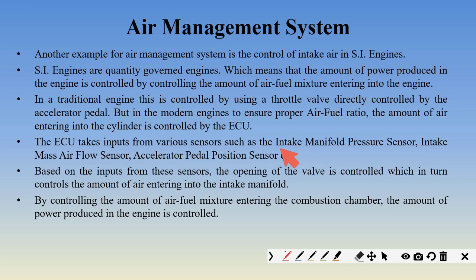So what are the sensors that will be used? Intake manifold pressure sensor, intake mass airflow sensor. Whenever there is mass airflow sensor, there is also an intake air temperature sensor. There will be accelerator pedal position sensor also. If he suddenly accelerates, the stepper motor should open completely, right? The valve should open completely. Therefore, an accelerator pedal position sensor will also be necessary. And what will be the actuator? The actuator will only be the stepper motor, right?